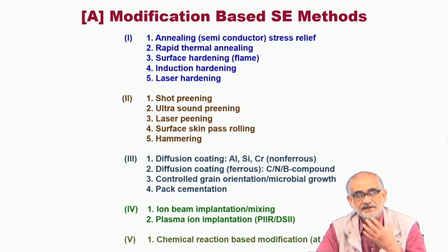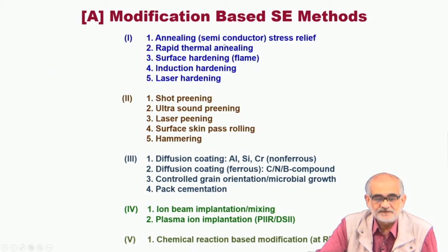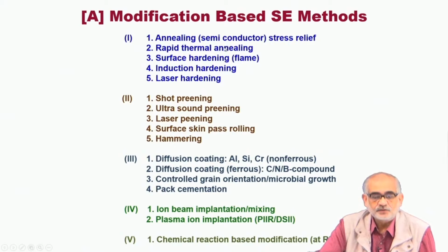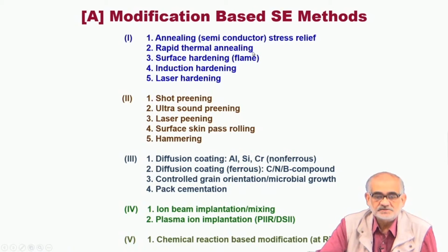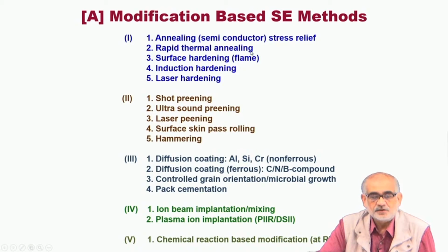So, you apply a flash of light, which could be a laser light or a thermal flash, because of which the surface gets activated thermally up to a very thin distance from the surface towards the core, and only a few atomic layers on the surface undergo thermally activated diffusion and atomic migration, because of which certain stress relief operations take place, or certain reorganization of atoms in small length scale.